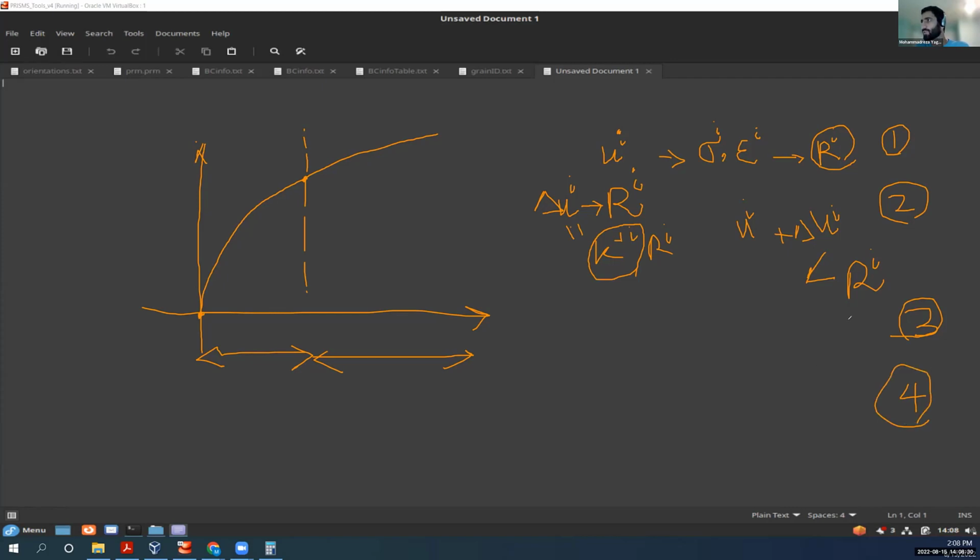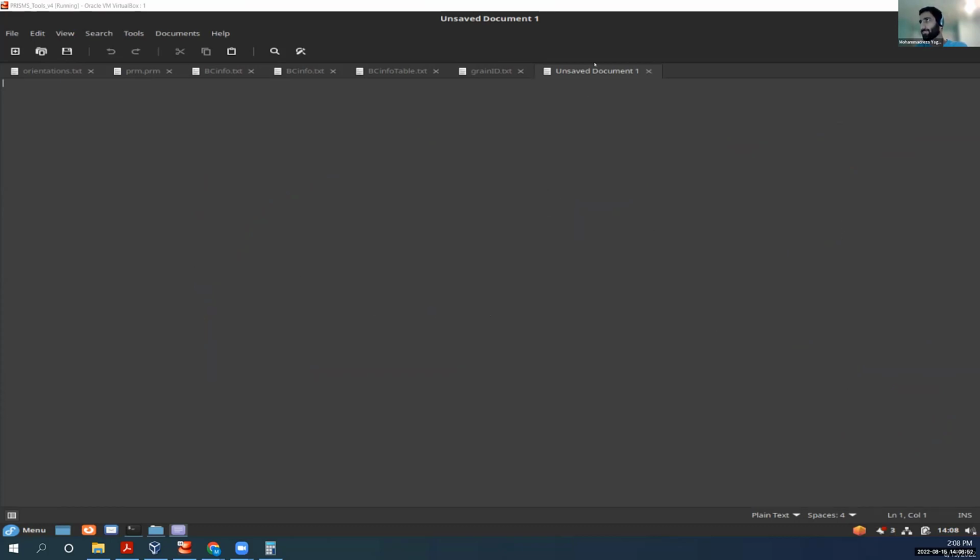If you repeat this again and again, that would be your convergence. This number here is what you know as the number of nonlinear iterations. So that's what I call the number of nonlinear iterations for Newton-Raphson for PRISMS-Plasticity, equal to 4. I think that has been clarified.